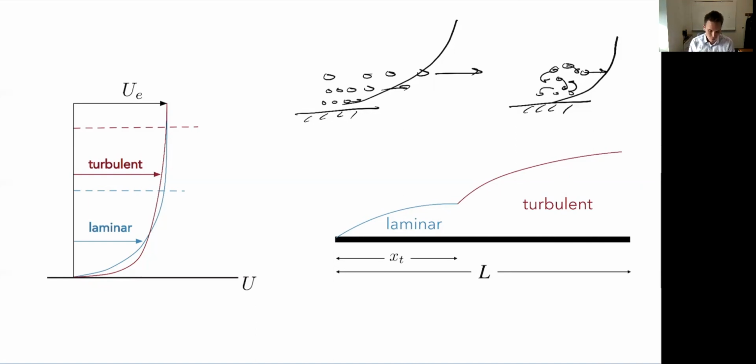In an introductory fluids class, you often hear this golf ball example. Just to recap, the idea is that rather than having a smooth ball, which will have more laminar flow, golf balls have these dimples to increase turbulence, to reduce drag.